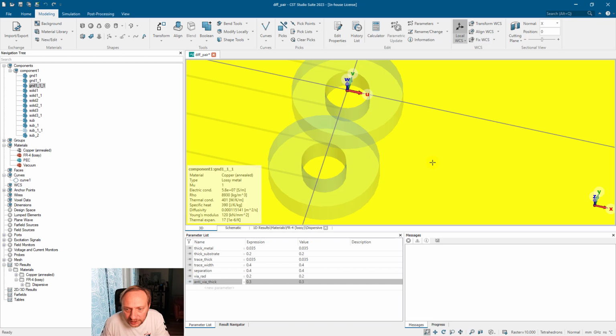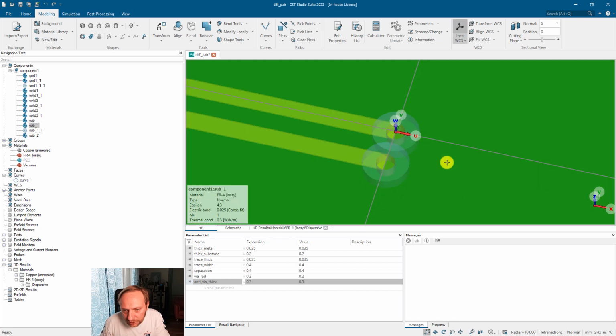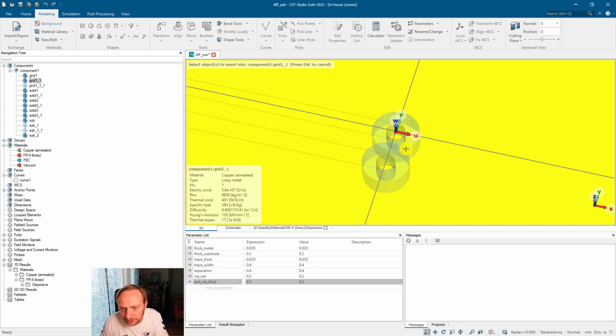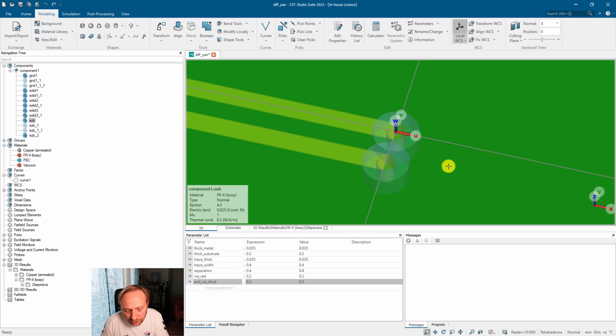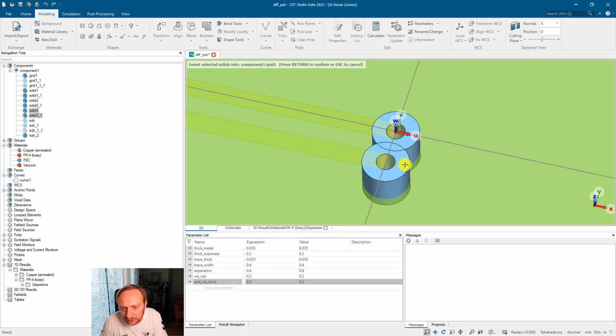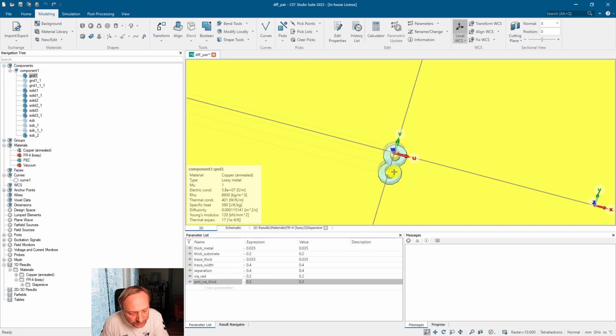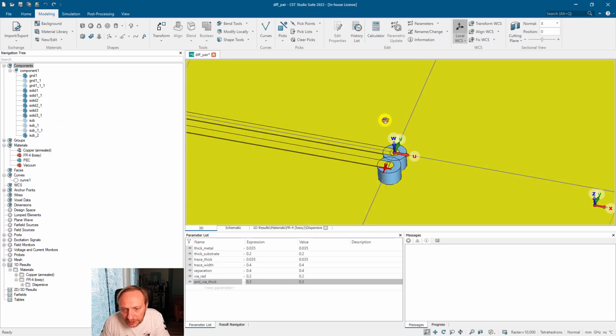So I double click the plane and hit the divide button, which is an insert command. This one and this one should be inserted into the shape, exactly. Control H, height, there's the next layer, divide, select, hit enter, we got our hole, Control H. In the substrate we don't need to do this cutout. In the metal again, divide, select, and hit enter. Now I got my holes. I don't need to care about this inner because it's overlapping with the via. So I got my holes, I got my anti-vias, I got the input here.